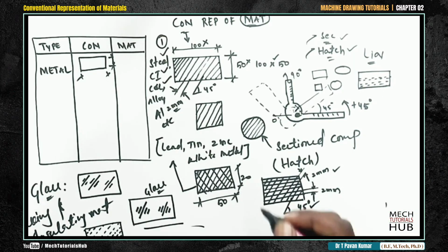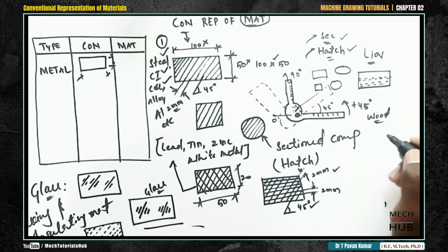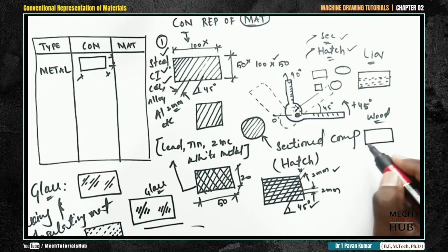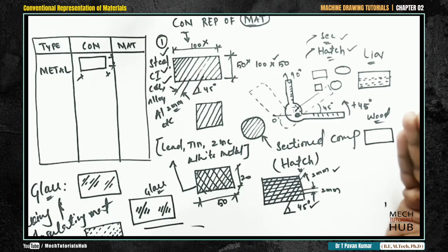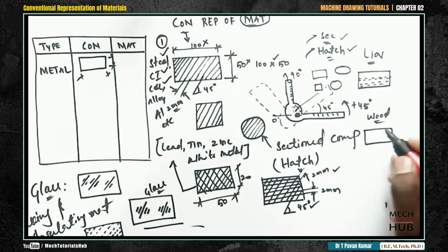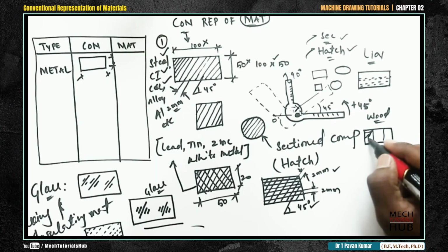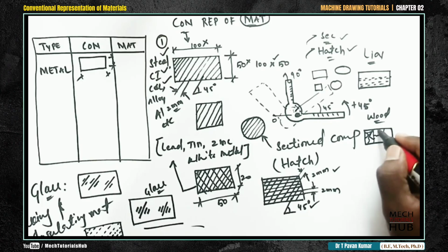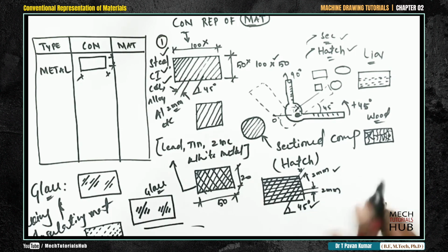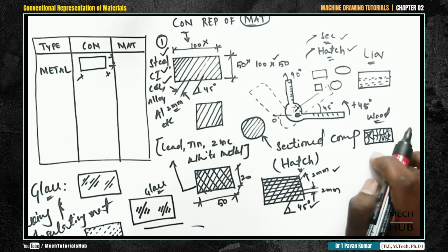Okay, in case of wood, for example, if the cut material is wood, same box of your convenient size followed by a dissimilar pattern. For example, if you cut a tree, the cut portion will look completely uneven. There won't be any proper uniform pattern. In such cases what we try to do is draw in a zigzag way with our free hand, like a spider. Okay, in a zigzag way, zigzag patterns we'll try to draw. Fine, have a look, we are drawing some zigzag patterns. This is the indication. There won't be any uniformity because it is made of wood.